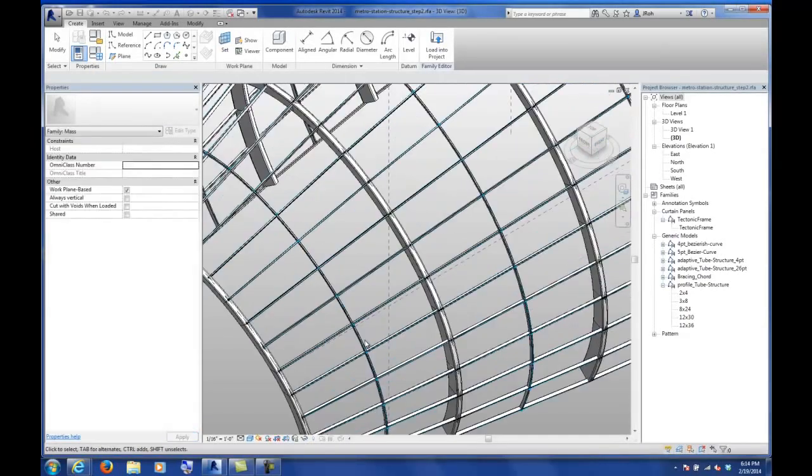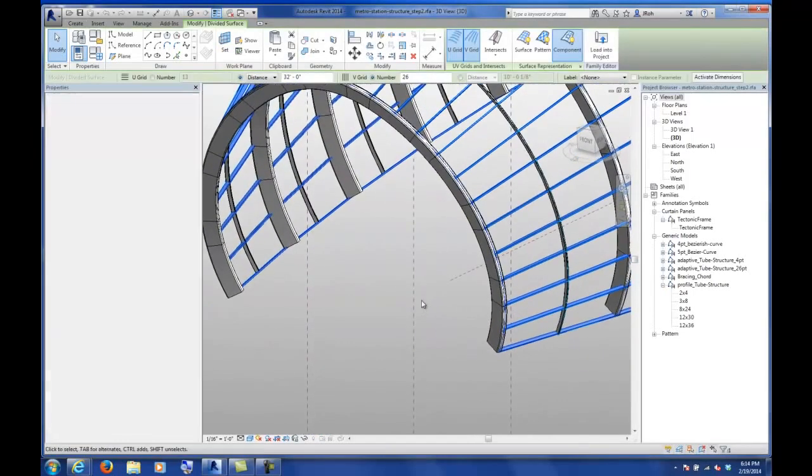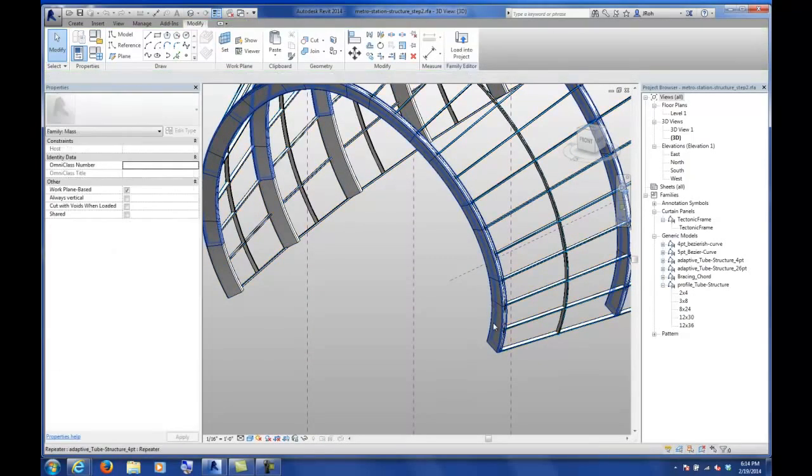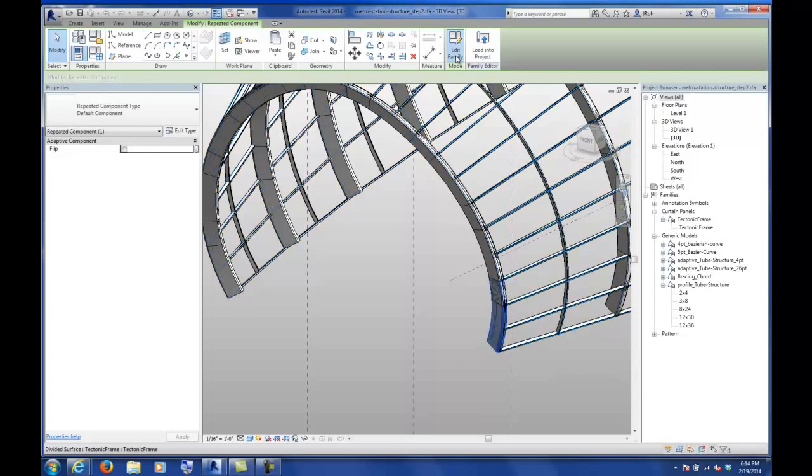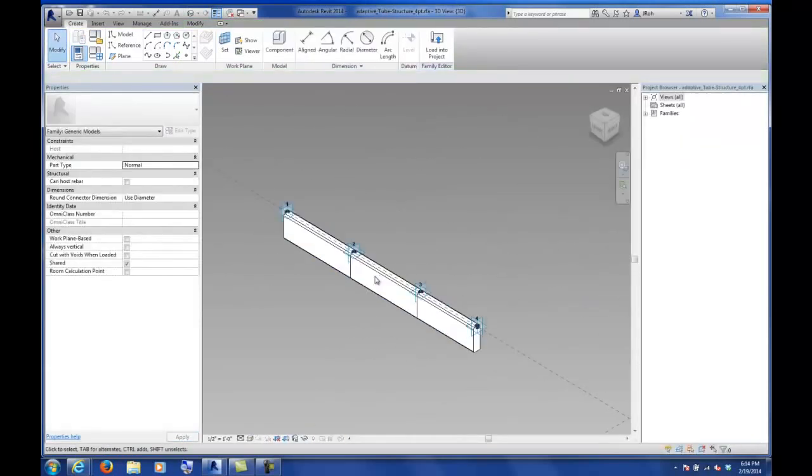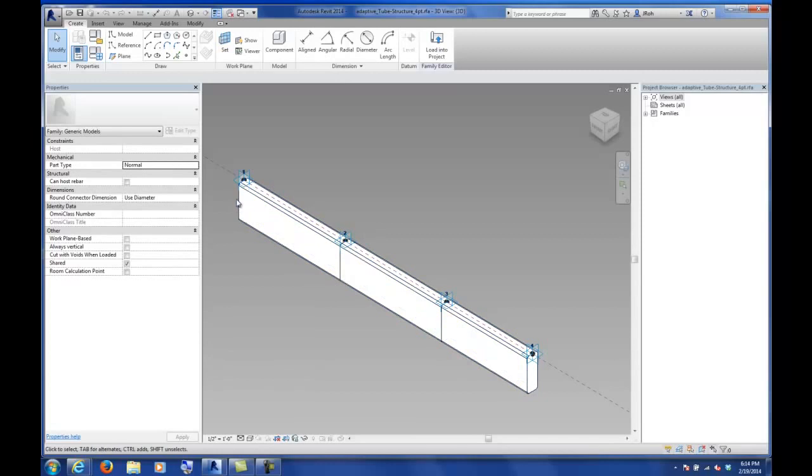We've been using these Bezier curves that we made. But this curved arch is made up of one adaptive component that's made up of 4 points. Each point had a hosted profile. We had this tube steel section that was hosted at each plane of those points, and when we snapped those to the grid, it stayed perpendicular the whole time. So the one thing you have to be careful of when you start to place more than 1 point is how your profiles eventually twist.